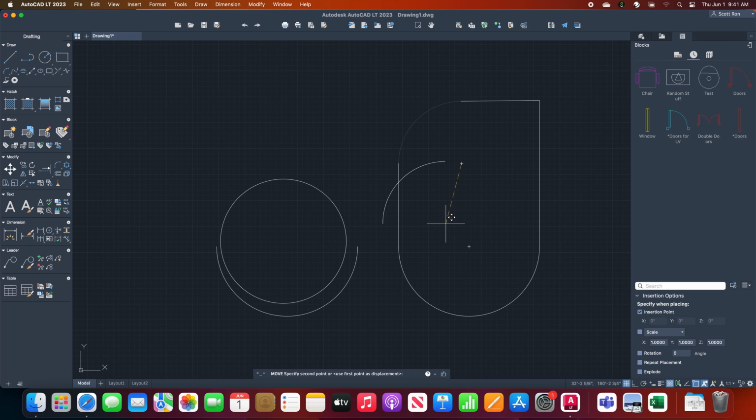No, it's not. What I was trying to say is that fillet works when it's an intersection, because fillet means smooth corners. But this line and that line were not joined together. This line and this line that was here were joined together. So when you're using fillet to somehow make a smooth, curved edge for this line and that line, instead of restricting it to 6 inches, it's just creating an arc that just joins it, whether it's 6 inches, 12 inches, or 15 inches.